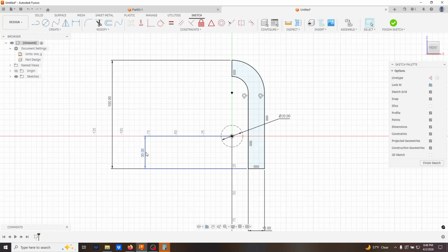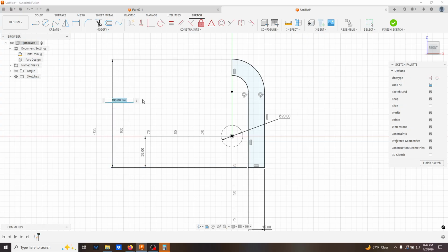But if I make this 29, and if I make this 99, both of these have a tolerance of plus or minus a millimeter. This distance right here, 29 minus 20, that'll give you 9. I would do a reference dimension here, but I don't feel like doing all that. Just 29 minus 20, 9 here.